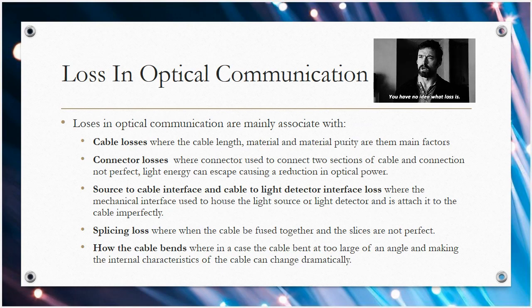Number 4, splicing loss, where the cable is fused together and the splices are not perfect. Number 5, how the cable bends, where in the case the cable is bent at too large of an angle, the internal characteristics of the cable can change dramatically.